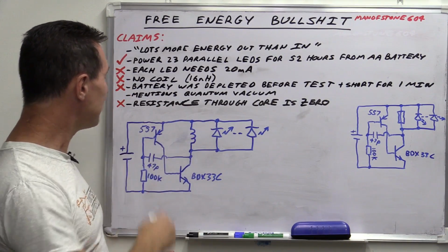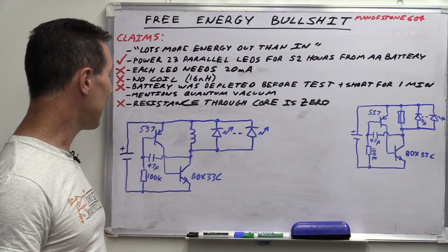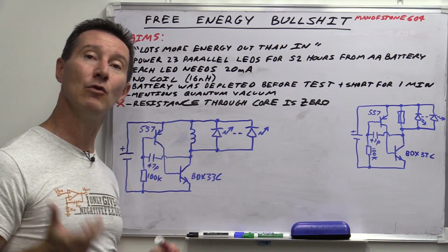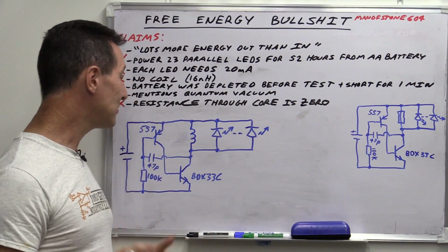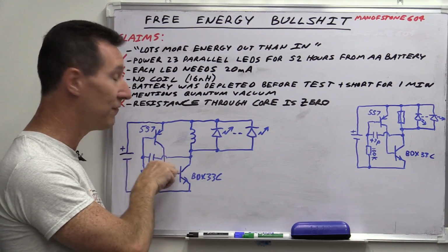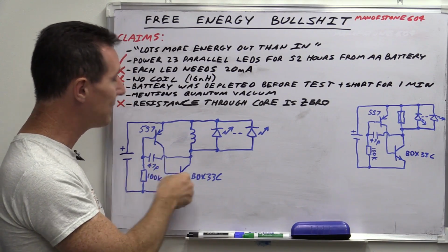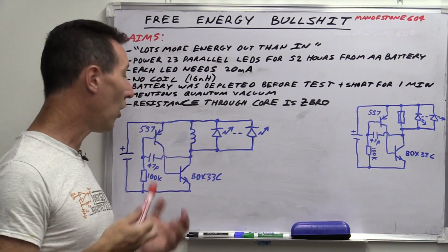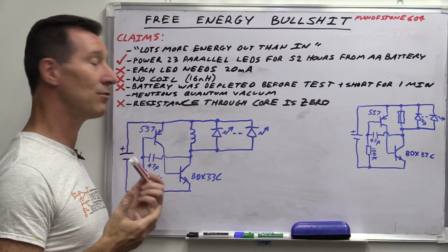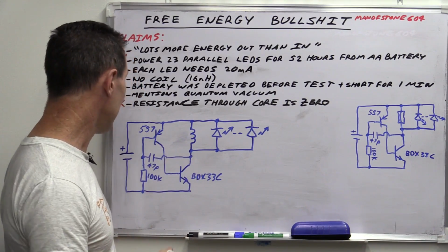So we've got a basic relaxation oscillator here. How do we actually start analyzing this? Well, for starters, when you first apply power, let's start looking for any DC paths to set these things up. Because we're using bipolar transistors, they're current-driven devices. You need current flowing in the base. If you've got current flowing into the base, then the transistor will turn on. So we're basically using these as on-off switches. They're not really being used in the linear way, hence the relaxation oscillator.